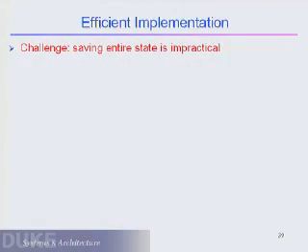So here's the algorithm for our spin detection. The observation here is that every spin loop has at least one backward control transfer instruction, such as a backward branch instruction or a jump instruction. We're going to implement our spin detector within the CPU core. Logically, every time the processor commits a backward control transfer instruction, we save the processor state. Then the next time the processor commits the same instruction again, we save the state again and compare these 2 states. If they're the same, then we say the thread has been spinning in between.